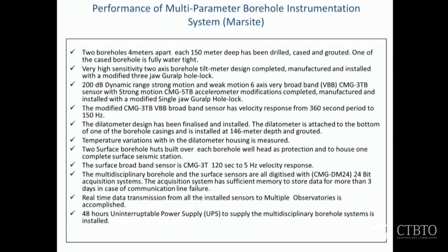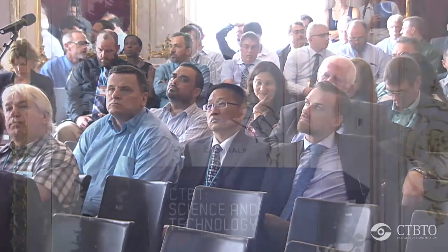Within one of the boreholes, we have a very high precision tilt meter, and in one of the boreholes we have a strong motion sensor, which is from Guralp, and a very broadband 3TB, again a broadband velocity sensor, but modified so that not only it's very broadband, meaning going down to 360-second period, but the high frequency end goes all the way up to 150 hertz. So the instrumentation installed is genuinely sophisticated. And the idea is that what can we do with this? There's lots of other types of devices in there, such as digitizers and power supplies.